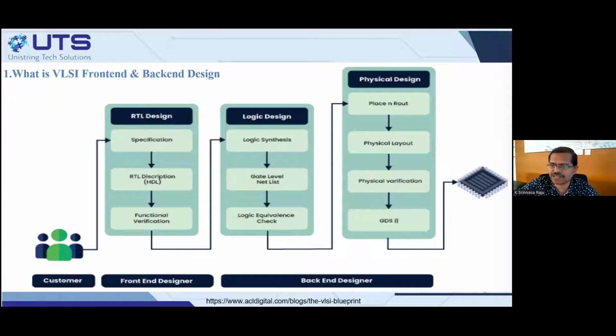It is only available at your desk. So instead of doing post place and route simulation here, I will just put it on the FPGA, and only where there are clock issues might I simulate those areas. Then you do the physical design. Some of these steps are not applicable to FPGA-based design. They are applicable to ASIC.